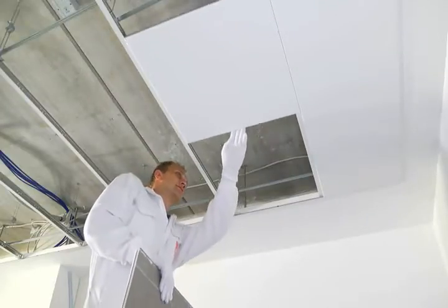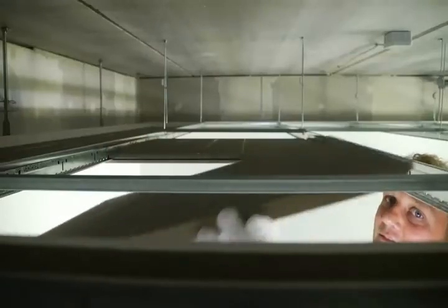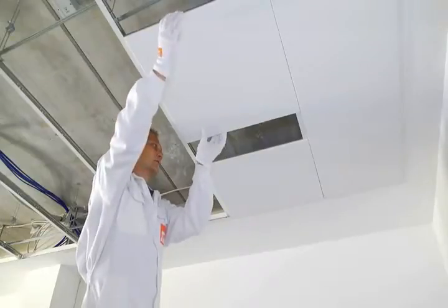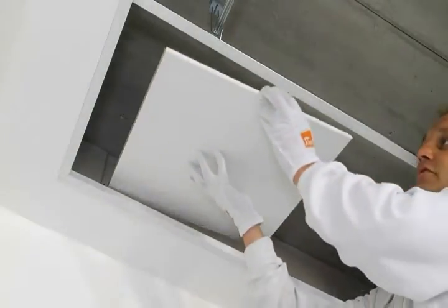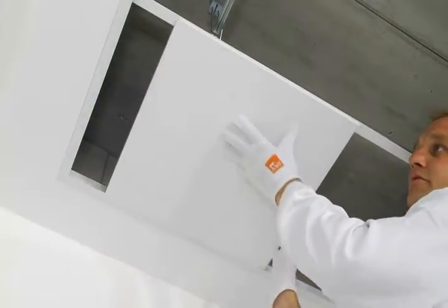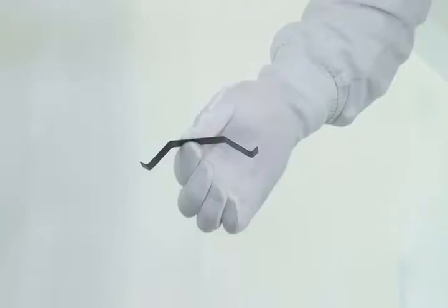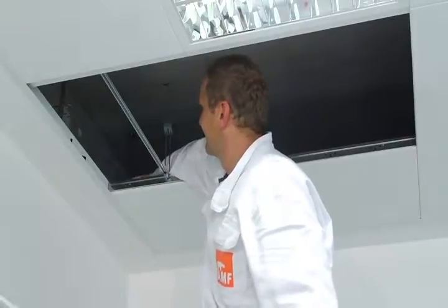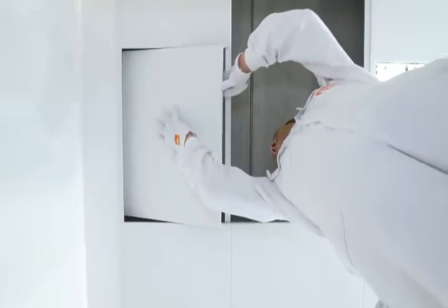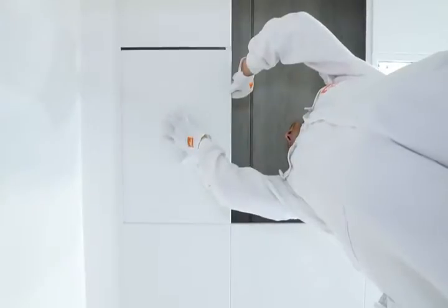To install the cut tile, the tile already installed is pushed a few centimeters to the side and subsequently pushed back. The ceiling is then completed row by row. The last 2 rows are installed together to enable easier installation of the 10mm smaller cut tiles with perimeter clips. The corner tiles, as well as both adjacent cut tiles, are demounted from the penultimate row. Every tile in this system is individually demountable for maintenance work.